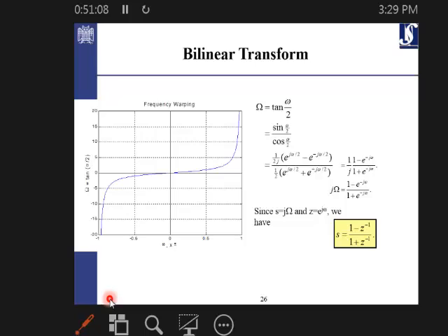So using this kind of transform, which is called the bilinear transform, for any sk that you make, you can just replace that in the form of the Butterworth design, or the first method of design. You have the e to the power of sk. Here you just use this. Instead of s, you can replace that with this bilinear transform. So any design that you made using Butterworth or Chebyshev, the sk values should be replaced with this fraction. Then what you get is a bilinear transform. The only difference is that the filter, as a result of this kind of mapping, is frequency selective.